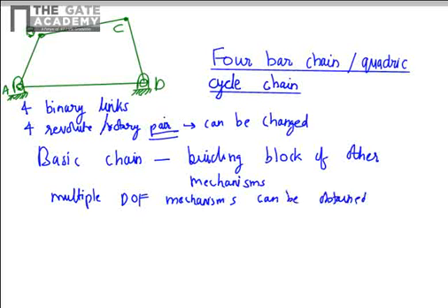If you see from the mobility perspective, you can visualize that a 2-bar chain lying in space may not serve any useful purpose. So there are 2 elements hanging in space. If you even fix one link, the other link just hanging in space by itself may not give any useful output. To form a 3-bar chain, the degree of freedom is 0 here. There can't be any movement. This is a fixed linkage.